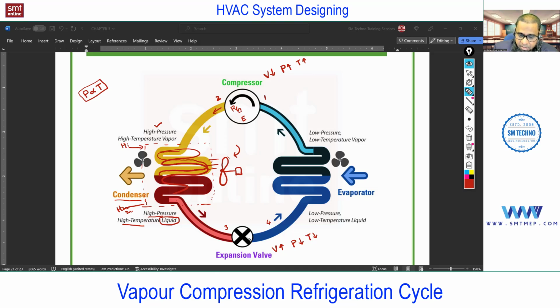And you see, when the refrigerant is coming out with the low pressure after this expansion process, the pressure is so low, some amount of refrigerant flashes and changes to vapor, by extracting the heat from the remaining liquid refrigerant. And we know that as the pressure decreases, the boiling point of the substance also decreases. So at the outlet of the expansion device, some amount of refrigerant will flash and extract the heat from the remaining liquid refrigerant, further cooling it down.